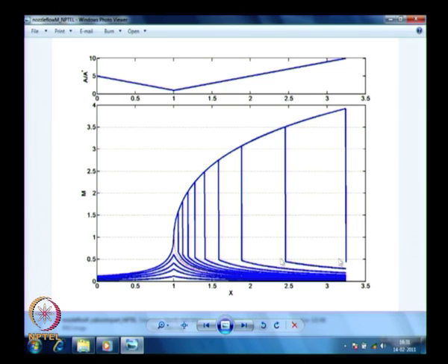If I decrease pressure further, it is going to go to even higher Mach number, and then from 3.5, let us pick, it is going to drop to 0.4 or so, it is dropping really high, while in the initial cases it is something of the order of 1.6 to 0.7 or so, rough numbers, okay. It is jumping only a little bit, and when I go to the highest case I have, that is probably 3.9 dropping to 0.4 or so, something of that order, okay. So, it is dropping really huge amounts, which means the shock strength is high. That is her way of giving the definition, right.